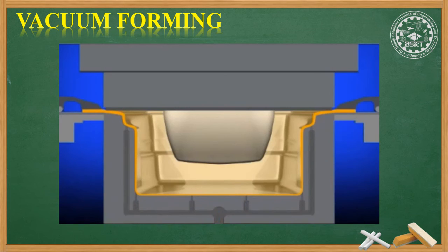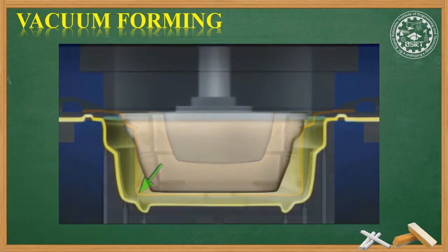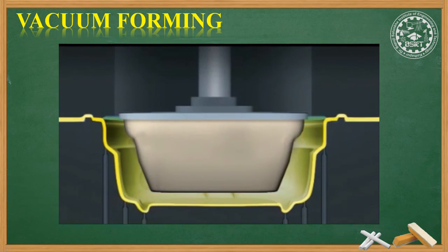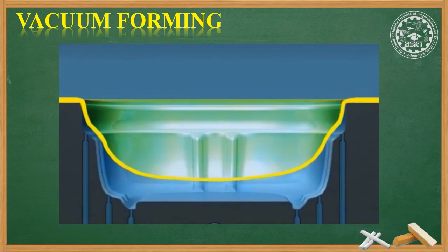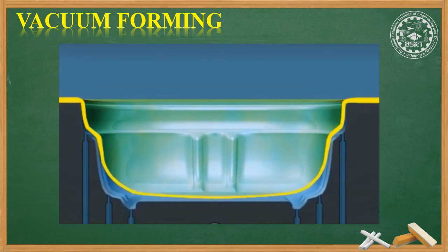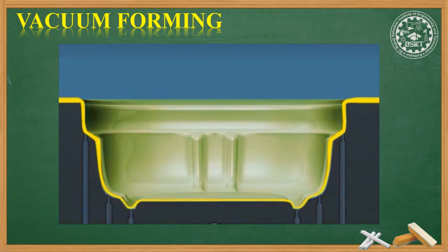The plug has pre-stretched additional plastic where it is needed. The shape of the plug affects the sheet distribution to improve the part thickness along the bottom and in the corners. A variation of plug assist is third motion plug assist, where the plug moves into the sheet after the mold is closed. Basic thermoforming causes the sheet to be thinnest where the plastic sheet is stretched the most.